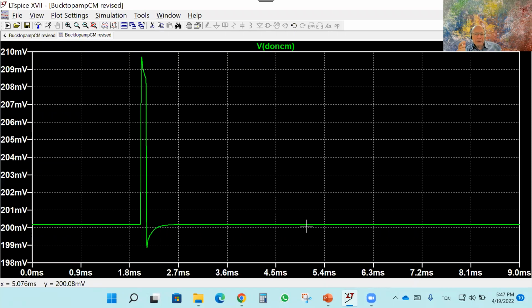So the actual duty cycle should change very little, only due to parasitics. So before and after the change, you see the duty cycle almost does not change. There is a disturbance here. It's trying to correct it very quickly by increasing the duty cycle, so as to build up a higher current.